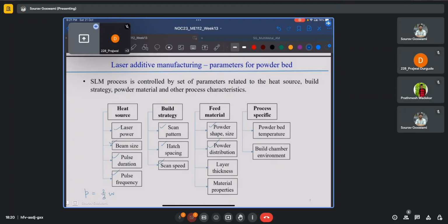As well as, often the minimum layer thickness is a function of the building process itself and it cannot be controlled. The material properties have to be evaluated and fed into any numerical model which is to simulate an additive process. And this becomes especially problematic for, say, new materials, non-standardized materials, or in the case of multiple materials, where we are not sure what properties to pick, in what ratio they should be combined, or if even a simple rule of mixture type formulation is sufficient. So we'll cover more of such aspects in the second slide for today.